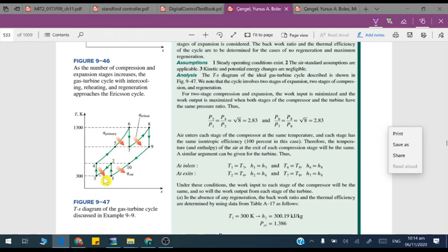So the temperature is 300, then you are increasing, ideally using the same compressor, meaning P2 over P1 and P4 over P3 will be equal. And then you are giving the heat, it is expanded in the turbine, so H6 over H7 and H8 over H9 will be the same. The turbines are of the same pressure ratio. In between these two turbines you are reheating.